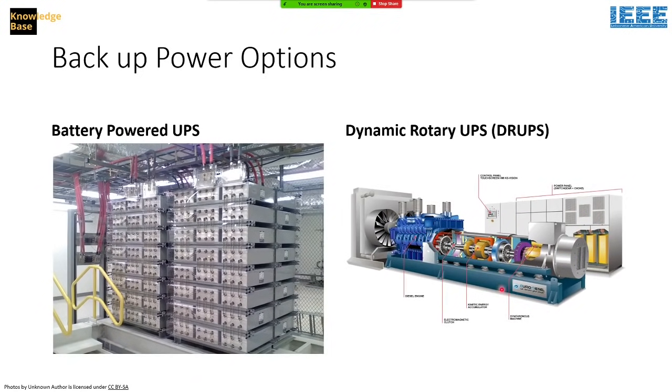So we have the generator and a shaft connected to the generator with a big flywheel around the shaft that is always rotating. It's maintaining its speed by the power of the utility. In case you have a power shutoff or power disconnection, this rotation of the flywheel turns the generator that is already connected to the system.